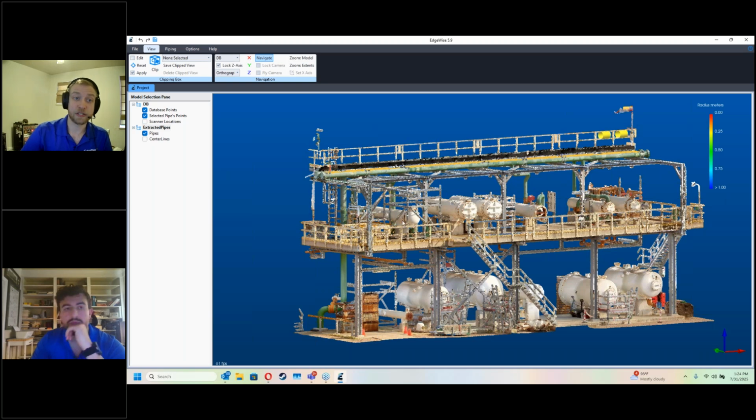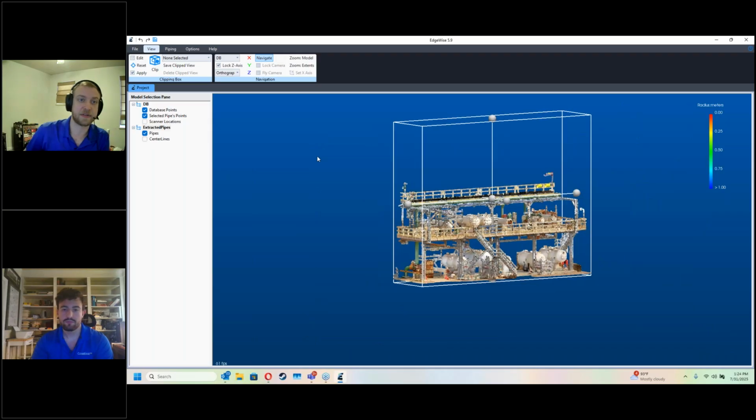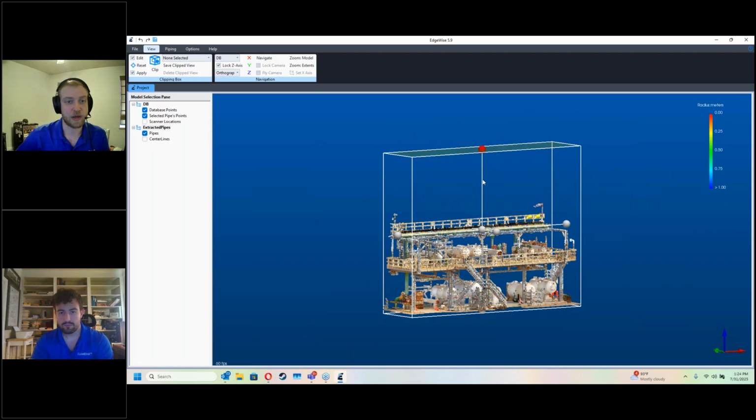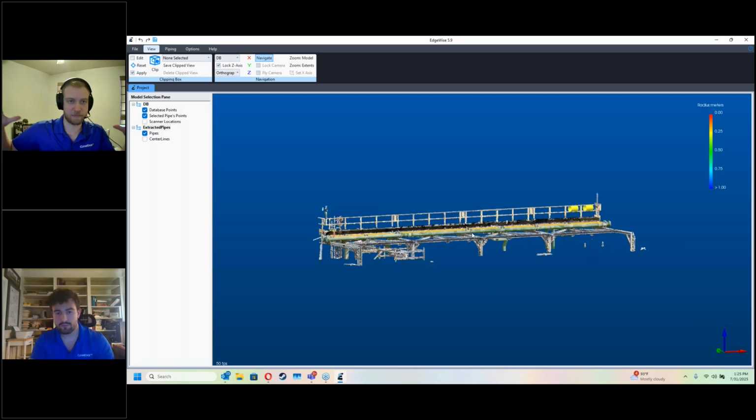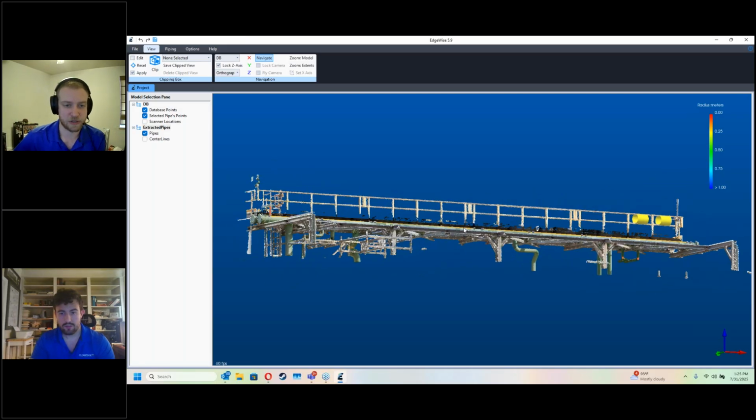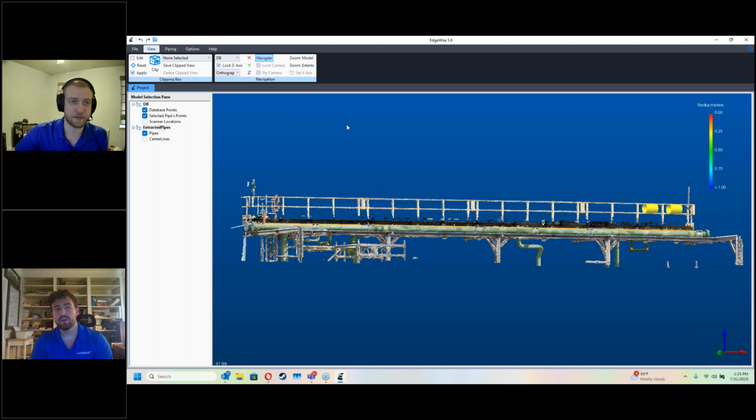The other option for doing something like that is the set x-axis, but that one's a little bit of a finicky button. I think that works in building, and it's better to use the clip function and these XYZ functions. That first click lets you start, and then you can get whatever angle you want and whatever view you're in to set the rest of it. So that's really the best way to modify it. I don't use the plain edit function, the big box, as much, because it's harder to get that rotation correct. So usually I use the clip function.